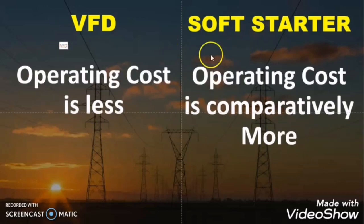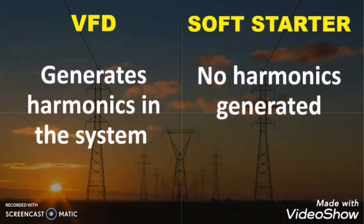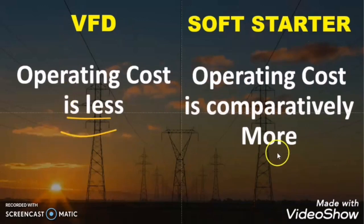Another difference between the VFD and soft starter is that the operating cost is less in the VFD, which I discussed here: when the motor is required to rotate at only 1500 and we can reduce the speed by using the VFD, it means we are reducing the operating cost. But in the case of soft starter, even if the requirement is to run the motor at 1500, we cannot run it at 1500. The motor is running at the rated speed, so the operating cost of the motor in the soft starter technique is high. So we can say that the operating cost of VFD is less, but the operating cost for the soft starter is more.